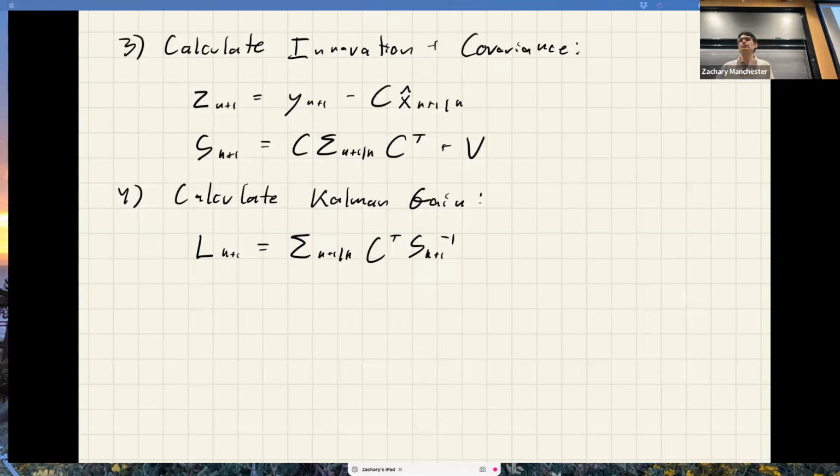And here we're not assuming that it's a unimodal model, right? We are. Yeah. You're assuming linear everything: linear measurement model, linear dynamics model, and Gaussian noise everywhere. So you're very much assuming the underlying statistics are Gaussian here. And practically, this works fine as long as it's unimodal, as long as it's kind of Gaussian. The noise is Gaussian, the initial state and everything is Gaussian. Yeah, because a Gaussian distribution propagated through a linear transformation stays Gaussian.